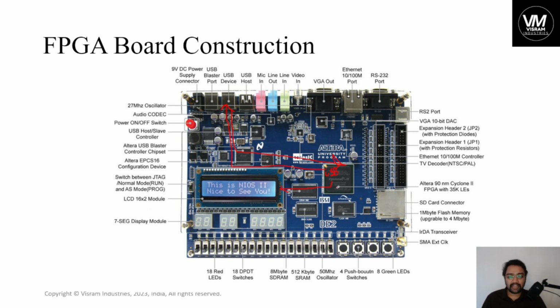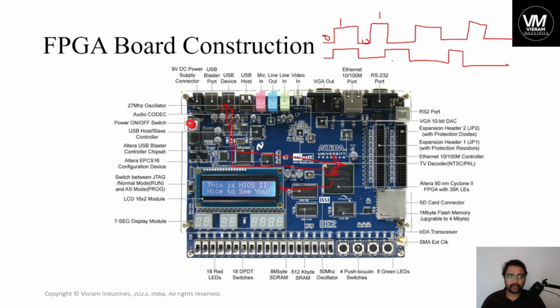In these central processing units, you will have a clock, which will be processing the data according to the speed and performance. Clock pulses are nothing but electric analog pulses, where 1 and 0 are the clock signals. You can see this clock signal like square blocks going on. Sorry about the bad drawing, but it can be 0 and it can be 1, 0 and 1. Imagine this is a uniform clock pulse. And 1 can be 3.3 volts, LVCMOS 3.3 volts, or 1 can be 5 volts. So 0 can be 0 volts.